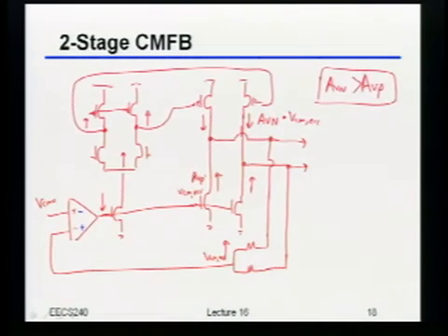Now, by the way, I can't really guarantee that, because I could have come up with some perverse sizing that didn't exactly do it, but most likely that's the case. But what this is really getting at is, don't forget, anytime you have common mode, you have to be really careful with how you tie those loops up. Because if you're not thinking about it carefully, you could very easily end up with some sort of positive feedback loop that you didn't intend.